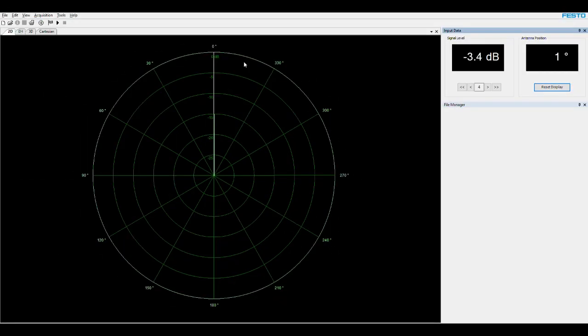Okay, so the purpose here is to study how the placing of my hand between the transmitting and receiving antenna will play a role. So to do that, let's start with measuring E cut of a half a wavelength dipole antenna when there is nothing between them. The reason that I'm repeating this measurement is that something has changed and it's not at the same time as previous measurement, so it's good to do another measurement to be consistent. So let's do that without having my hand.